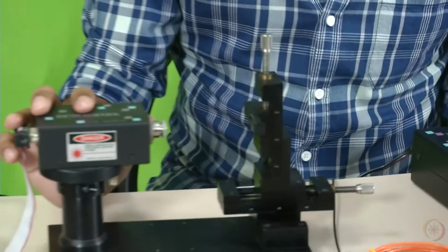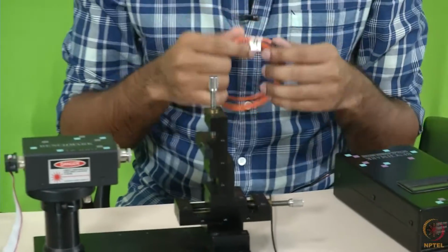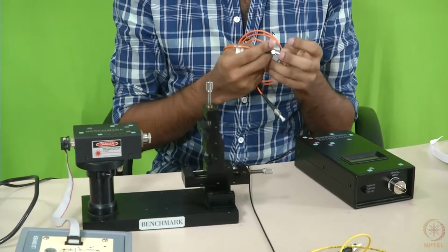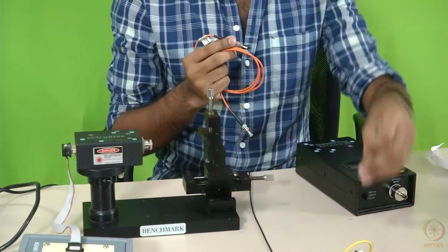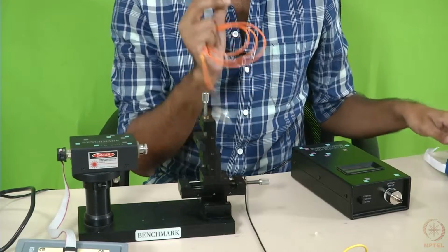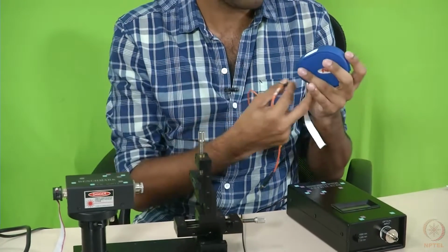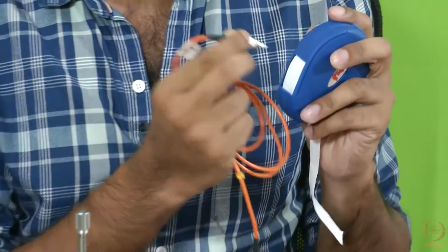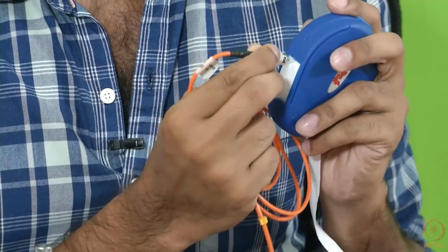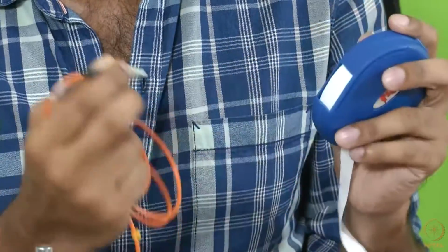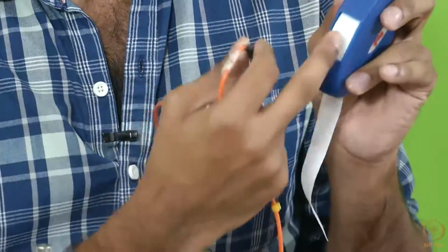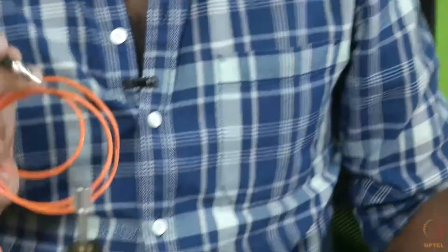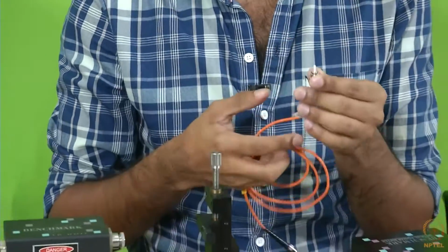We are going to turn on this laser. We are going to attach this fiber here, the other end here, and see the power. For all the optical fiber based experiments, it's a very good practice to clean your fiber tips. So you have your cleaning paper here. You rub it 3 or 4 times in the same direction. Lift, rub, lift, rub again, like this, in different spots of the paper. And then once you feel that one section is slightly dirty, you pull it like this and keep doing that. That's how you ensure the fiber tips are devoid of any dust.